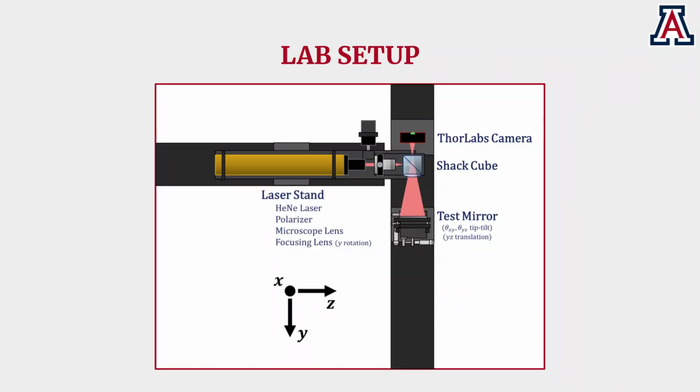To test, first slowly add defocus in and out of best focus and record the fringe count, spacing, and radius at each increment. Return to best focus and repeat with both vertical and horizontal tilt, as well as horizontal tilt with slight defocus. Lastly, repeat all tests instead with the short focal length test mirror.